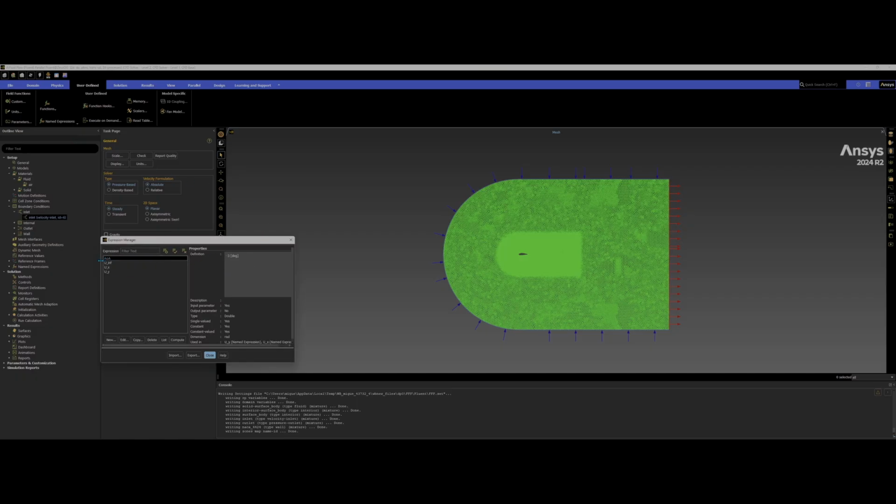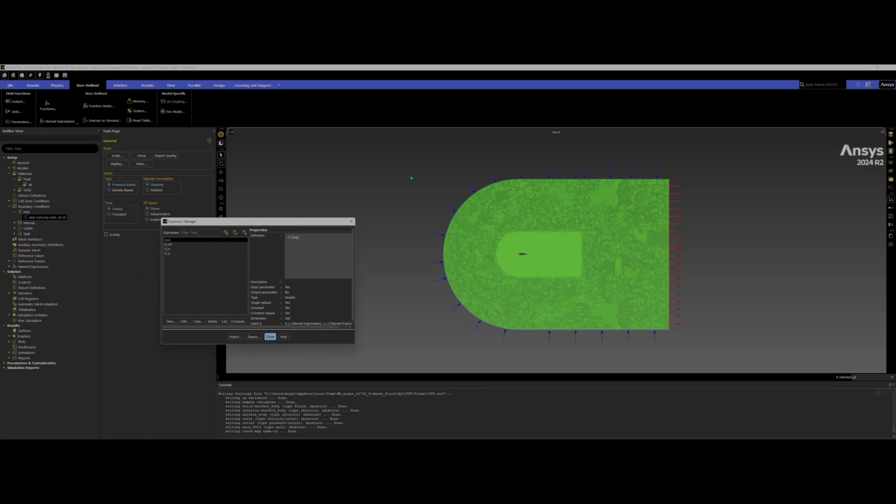Always check the units. For angle of attack, they'll always say radians instead of degrees. That's because ANSYS would always convert from degrees to radians. So do keep that in mind. This can be changed in the workbench once we finish here in Fluent. But it is still -3 degrees. Just keep in mind that when it says dimension radians, it just means it's converting it to radians because ANSYS just likes radians. Here, meters per second, good. And it is important, make sure all this is meters per second and that your formula is correct. Right here, and there you go.